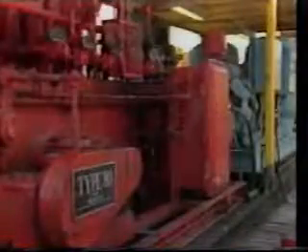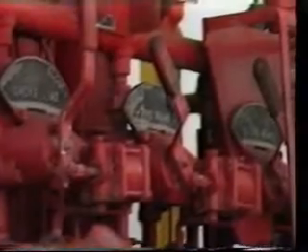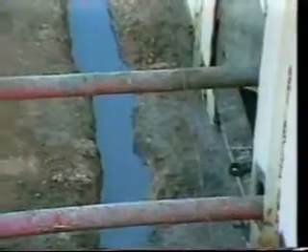Blowout preventers are opened and closed by hydraulic fluid stored in an accumulator and controlled from either the accumulator itself or a control panel on the rig floor. Once a kicking well has been shut in with the BOPs, the high-pressure formation fluid must be circulated out of the hole and the mud system adjusted to contain the pressure before drilling further.